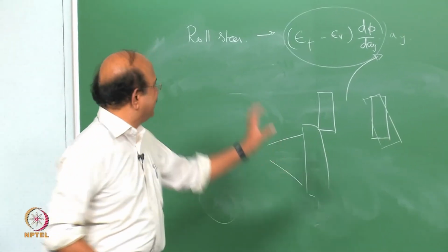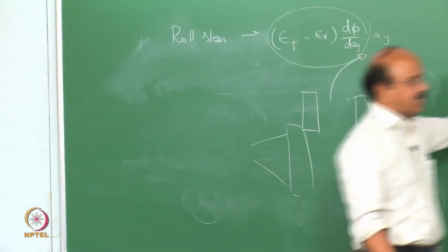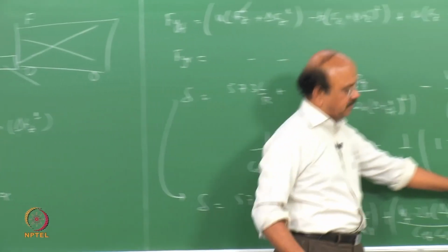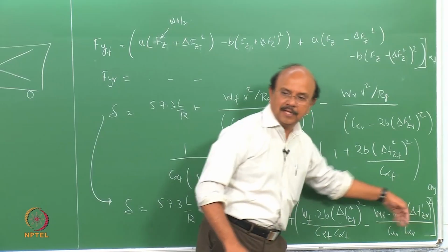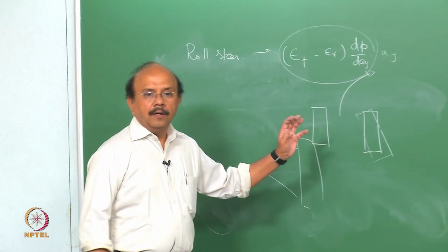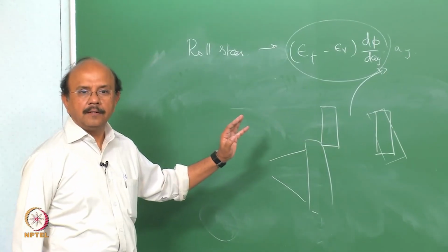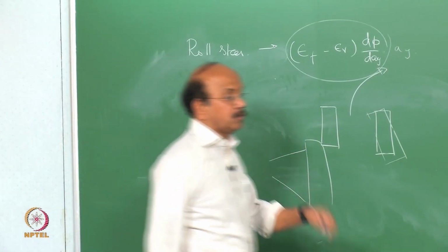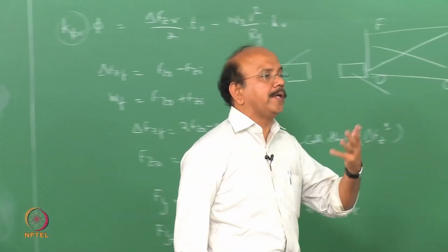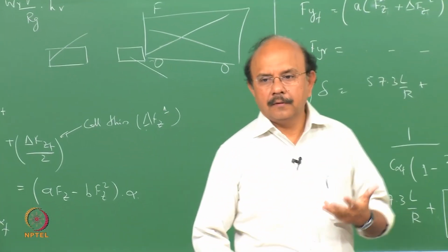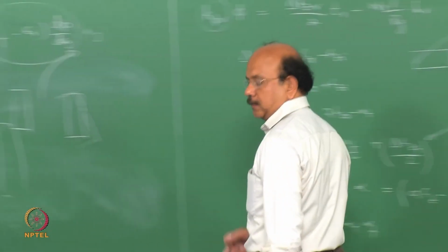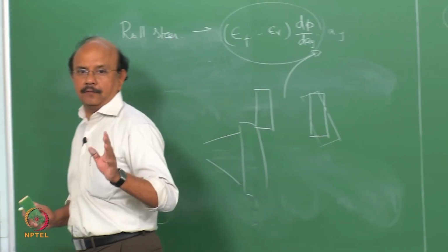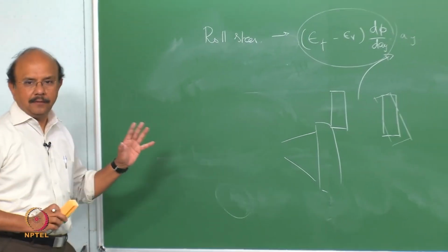This is what comes inside the bracket. So this is what is the understeer. Whatever is coming inside is what is the understeer gradient, which we called K2, if you remember, in one of our earlier classes, and that's what would go into that expression. Clear? Any questions? So this is called the roll steer. So people actually plot how toe varies as you roll. That's a part of your exercise in the next course, so don't worry about it right now. But you would look at that closely.